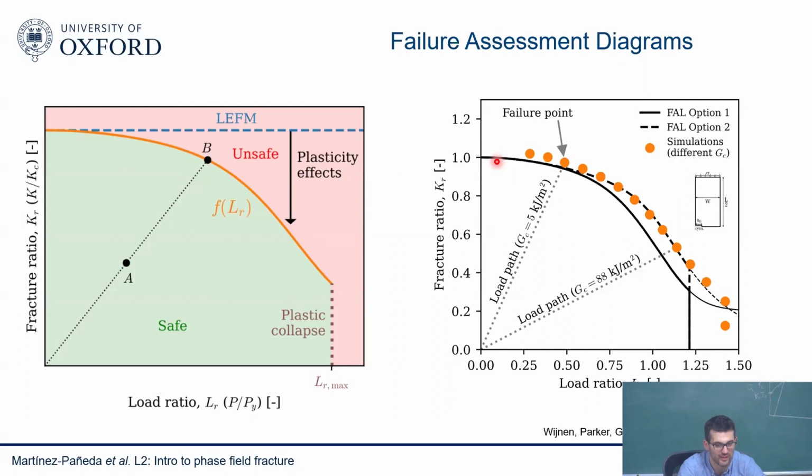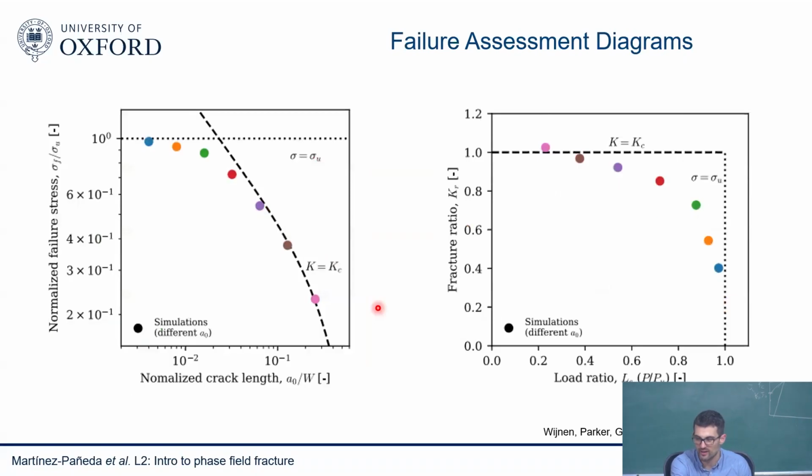So all these J-integral ideas, all this elastoplastic behavior is naturally captured in phase field. And this is, again, quite convenient because whatever I do is going to be in agreement with the standards, in good agreement with well-established fracture mechanics theory. And in fact, you can take a failure assessment diagram and do the same thing.